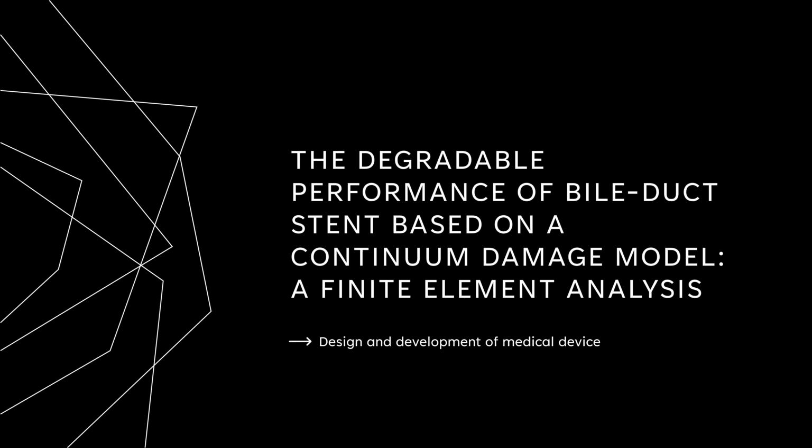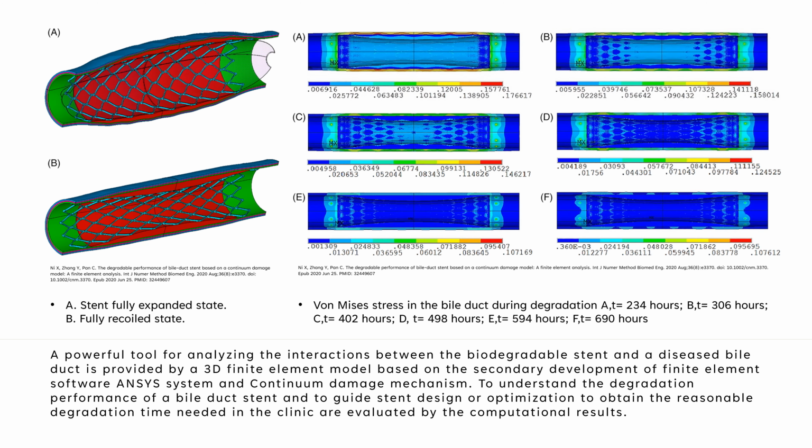And the last one is about medical device design and development, the research titled The Degradable Performance of the Bile Duct Stent Based on a Continuum Image Model, a Finite Element Analysis. It is the goal of this study to, first, develop a finite element model based on a continuum image model that is capable of modeling the corrosion of a bile duct stent using elements birth and death technology of software ANSYS. Second, apply the model to better understand the mechanical performance of a bioabsorbable bile duct stent during stent degradation.